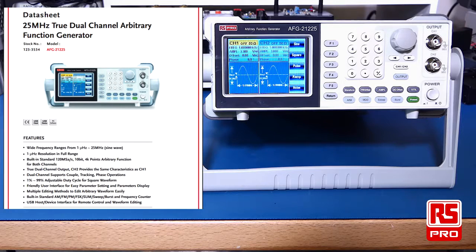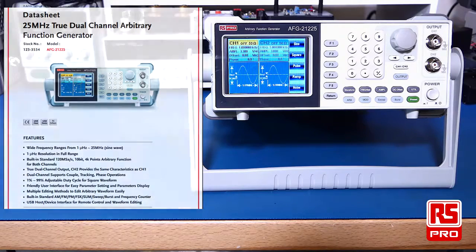The duty cycle for square waveforms can be adjusted between 1 and 99%. As standard, it has built-in AM, FM, PM, FSK, SUM, sweep and burst, as well as frequency counter. It provides multiple editing methods to edit arbitrary waveforms. These can be either done on the device point to point, imported via CSV file, edited on the PC application, or captured from other RS-PRO oscilloscopes and imported to the RS-PRO arbitrary function generator.